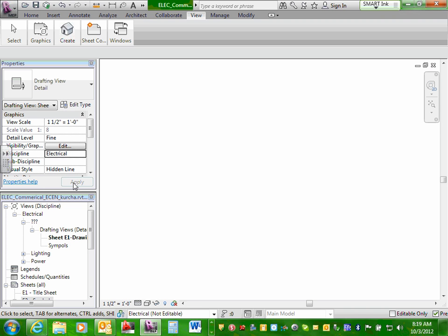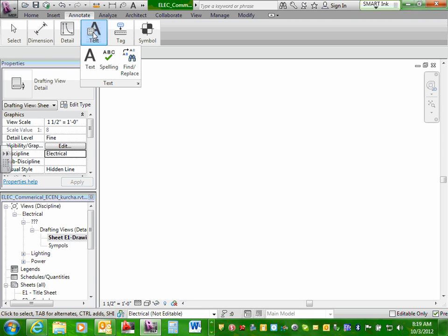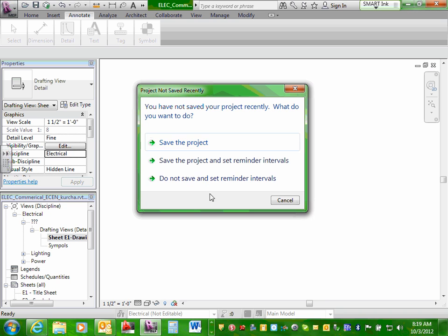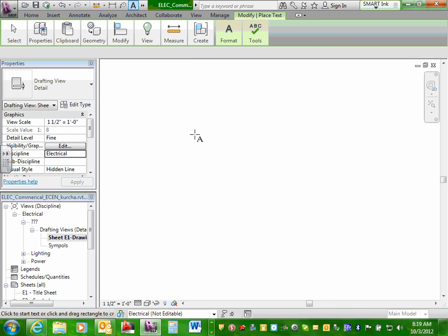Now, I'll hit apply. What's at the bottom right here? Oh, it shows. Okay, that's good. Do you see it under, like, right with the symbols? Yeah. Okay, cool. Now right here, guys, I want to type text. So I want you to go, I believe, Annotate, Text. Can you guys see the text? Everyone can see Annotate, Text. I'm grabbing a text, any text for the time being. Okay, save and synchronize. Let's save the project here.